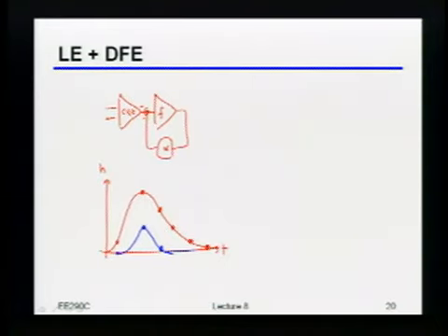Right? Well, now if I have even just a one-tap DFE, how should I readjust my continuous time linear equalizer? What do I want it to do now? Leave the first post-cursor alone. Yeah, I just want it to leave the first post-cursor alone. Why is that actually good? How does that help me? It improves the amount of swing you have available to transmit. Yeah, exactly. Basically, I'm doing less equalization, so the amount of DC gain that I'm throwing away is smaller.